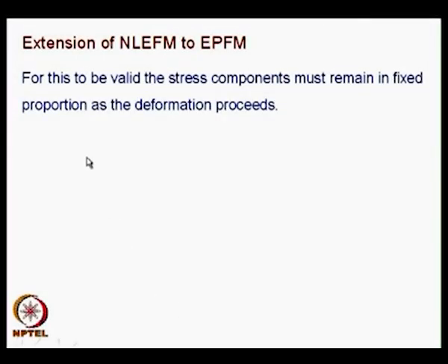And for unloading not to occur, or if you want to extend the concepts of NLEFM to EPFM, the stress components must remain in fixed proportion as the deformation proceeds. This is called proportional loading, we will see that in detail. So, in all fracture mechanics literature, you will come across a terminology proportional loading when you are discussing concepts related to EPFM. And what is proportional loading?